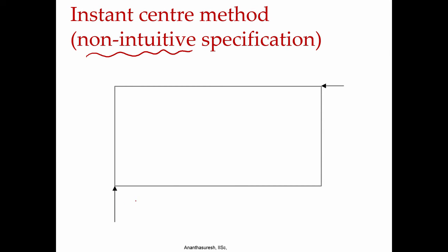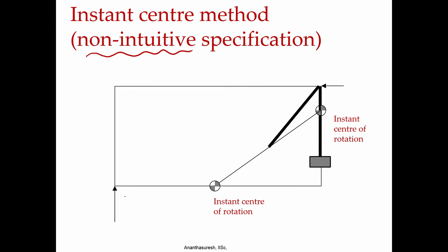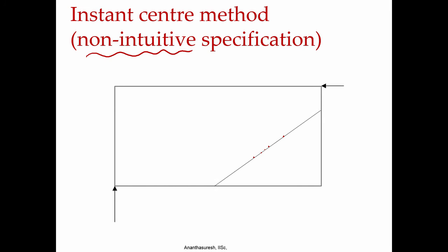So what we do is we take an intermediate thing and choose 2 instant centers, one here and one there, so that we can put together 2 blocks to get what we want. If you do that, the first one, and also choose a point, you can choose a point here, here, anywhere, does not matter, you choose a point. First of all, there is a choice in choosing first that direction, okay, that direction we first chose, and then the point later. Once you choose the direction, instant centers get fixed.